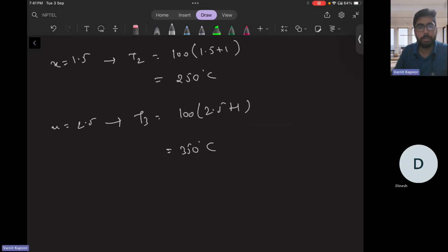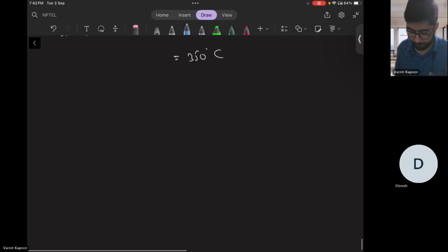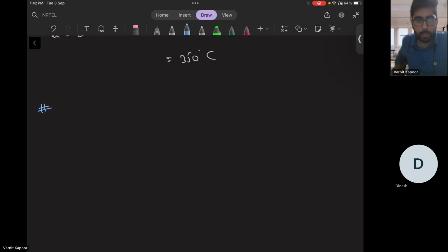Now let's come to the linearization of the source terms. Because we have done that case in the previous tutorial, where we were just writing the linear form of the source term. But what if the source term depends on square and cube terms as well? Let me write the heading. Source term linearization.